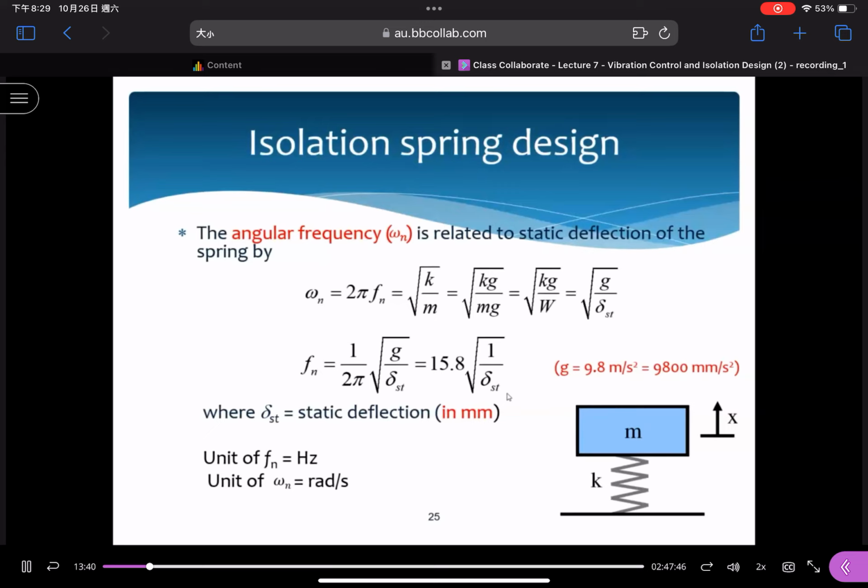And this one, spring connections, there are two forms. The first one is in parallel. In parallel, you just need to add all the stiffness together. Okay, no matter whether they are equal or not, you just add them together to find the equivalent stiffness. If they are connected in series, you may refer to these equations. They are different. I have two examples in your lecture notes to show the difference between them.